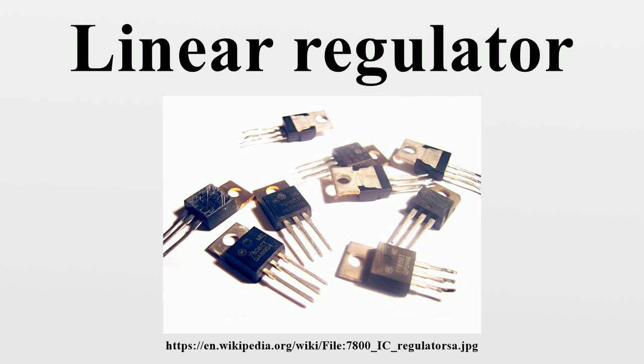In fixed voltage regulators the reference pin is tied to ground, whereas in variable regulators the reference pin is connected to the center point of a fixed or variable voltage divider fed by the regulator's output. A variable voltage divider such as a potentiometer allows the user to adjust the regulated voltage.